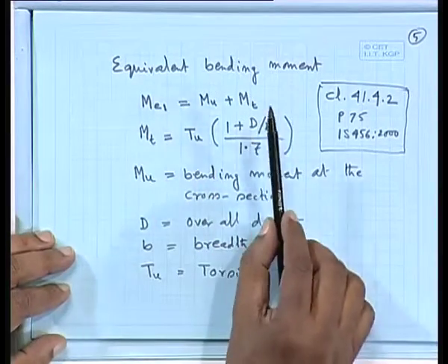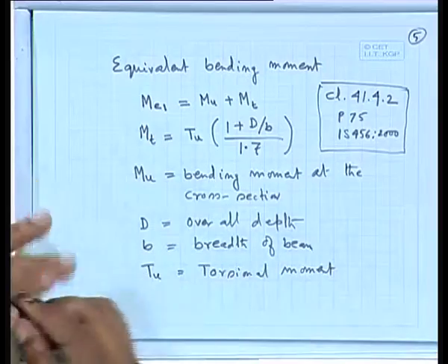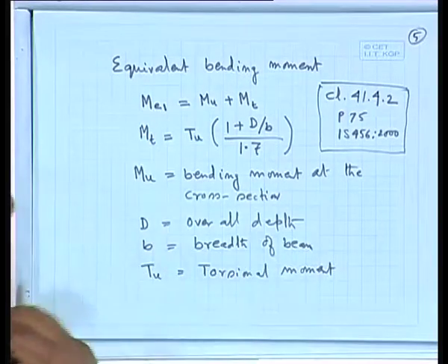But finally we come to this 1.6, 1.7 for design purpose, so that it is applicable for a wide range of, say, rectangular sections or beams. That is the objective here, how we generally come to all the clauses wherever you have different parameters. Sometimes we find out something, say modulus of elasticity, E, that is 5700 root over fck. If one is interested in design, from the analysis or from the experiment, one can find out the value, maybe it is coming 5200 or 5300, but finally we come to that particular value so that it is applicable to a wide range.